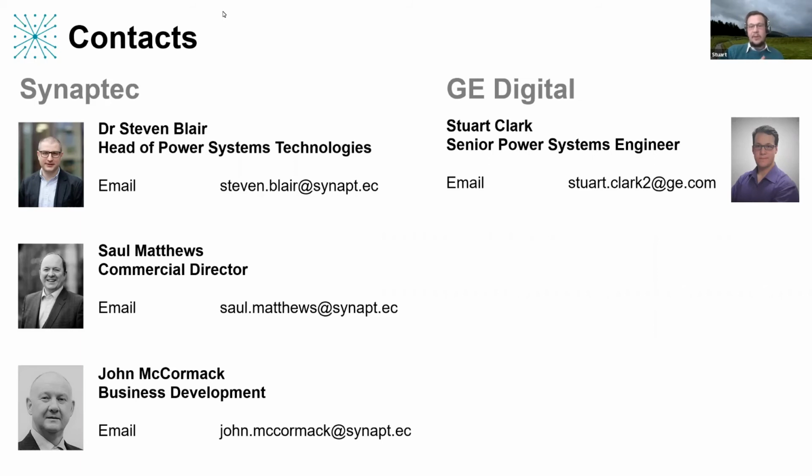So if you think about it in a WAMS, if you have 100 PMUs in your system, every one of those PMUs will send you a data packet every 20 milliseconds, and the job of the phasor data concentrator, whether that's a first hop in as an intermediate regional data concentrator, or it's the final destination at your control room, is to receive all of those packets for each 20 millisecond sample, align them, combine them into a single time slice, and pass them on to any consumers or any historians or wherever that data is going to go.